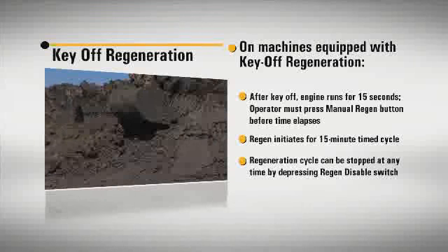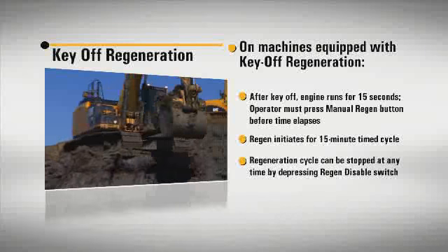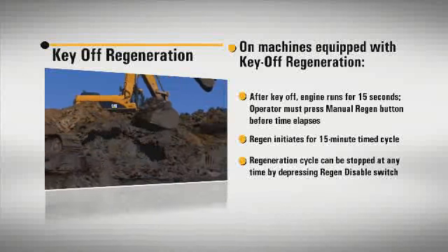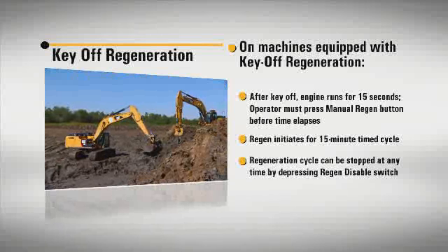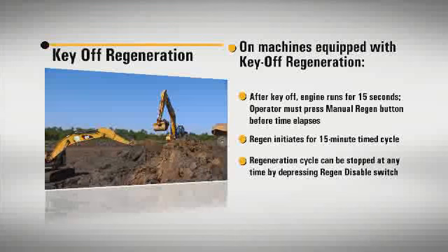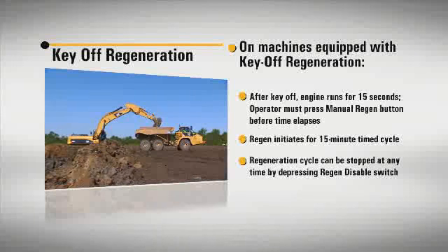Be sure to check for any rules or regulations that apply to your work site regarding unattended machines. Someone may need to be assigned to monitor machines as they regenerate. To meet U.S. OSHA worksite regulations, for example, someone must always stay within 25 feet of a running machine.